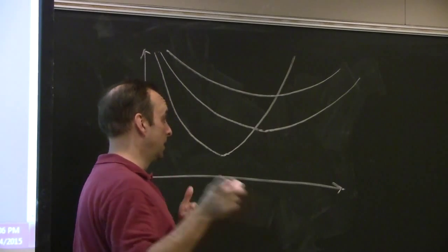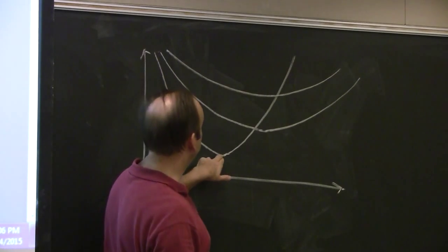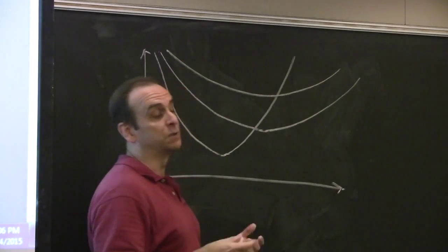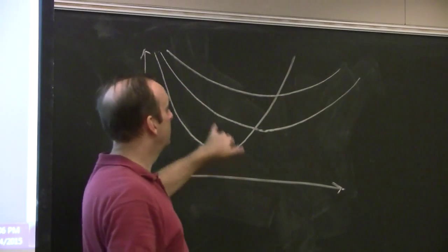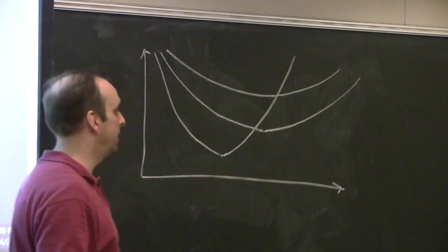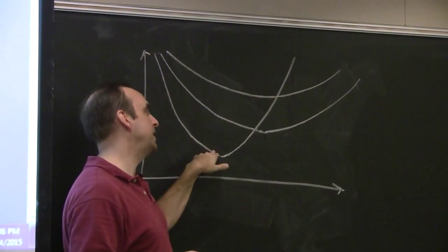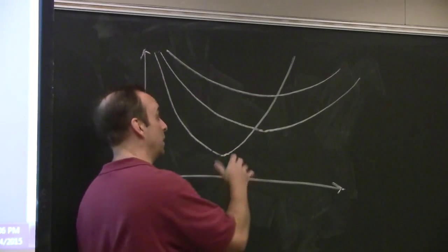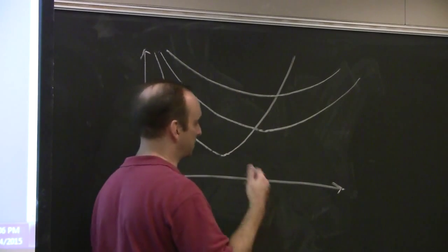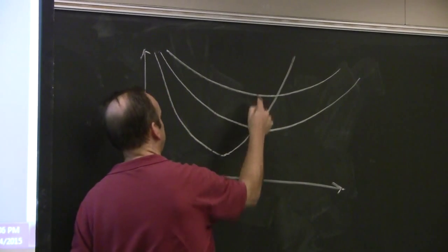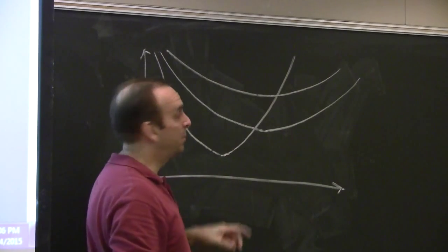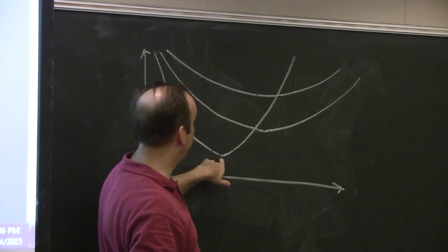So, to answer your question, is this resonant point so far out that it has no impact? The answer is no. It actually does have an impact. So the way you counteract that in designing a board is you actually incorporate several stages of capacitance, if you will. So the overall system capacitance or system impedance is the vector sum of all of these guys. But yes, this resonant point of capacitor is an issue.